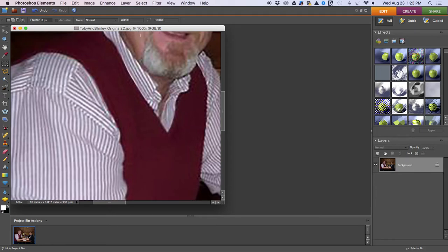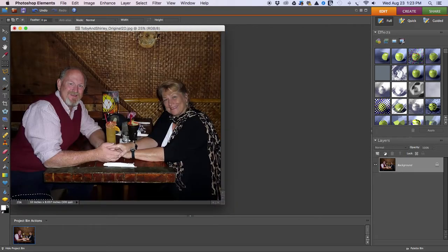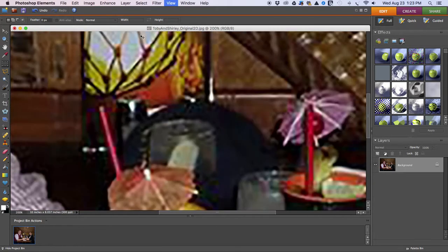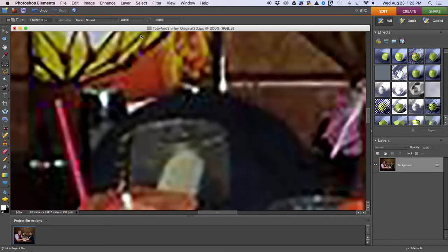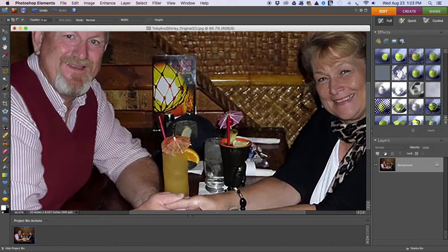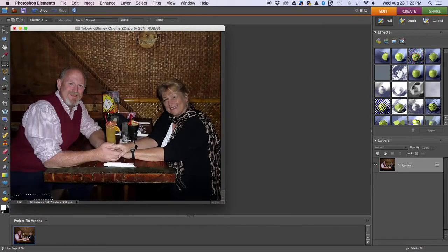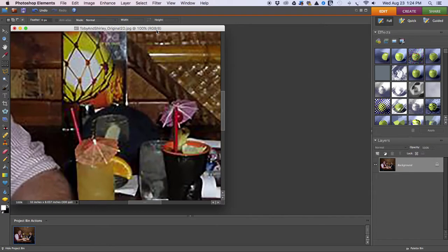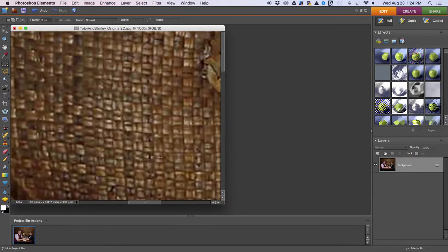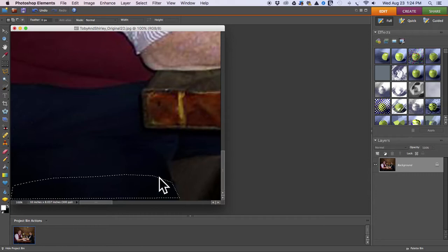So, doing the conversion as you're drawing your selection lines and doing your work, you might view it at various sizes. You might go back, zoom it out. You might zoom in really, really close, 300% now, to get real accurate with selecting around something. And that's fine, but every time you're ready to do your shift, when you've got your selection lines drawn and you're ready to shift them, go back to viewing it at 100%. So Command Option, and I'm on a Mac computer again, so Command Option and the number 0, and that brings you back to 100%. So we're at 100%, and we're going to want to move this.